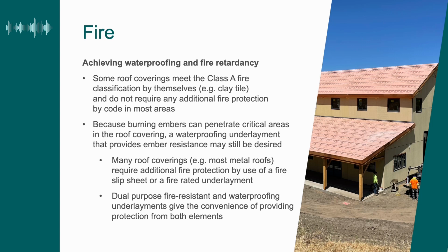Because burning embers can penetrate a lot of various products because they're not sealed. Most of everything on a steep slope is overlapping. It's not airtight, therefore it's not watertight, therefore it's not completely tight to things like small flying embers. The picture is just giving you an idea.